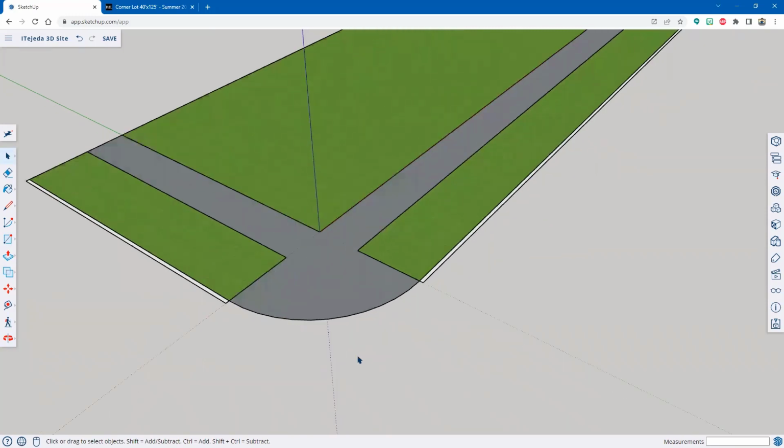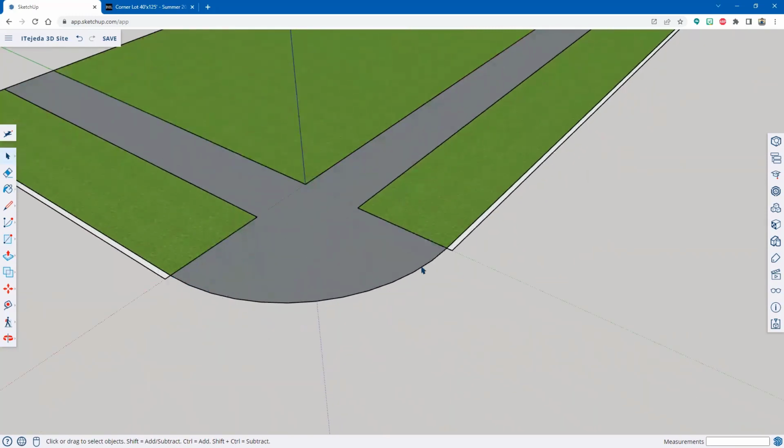And then finally, I need to get this arc in there. I actually need to draw 2 arcs. So here we go. My arc keyboard shortcut. I think if I type A, it says click to set start point. I don't know if this is it. So let me actually tap my space bar and I'll go back here. Yeah, see, I don't think that's going to work. I think I need to come over here and actually click on arc. That way it gives me the center point. Yeah, center point is critical here.